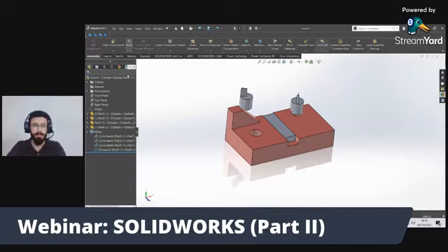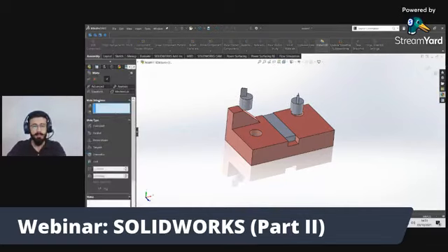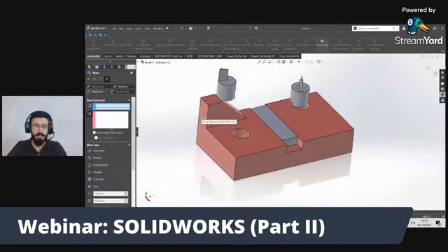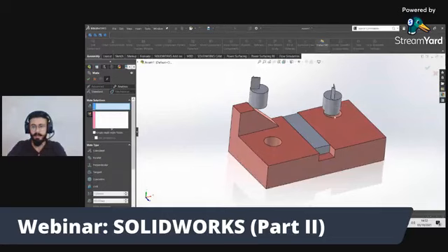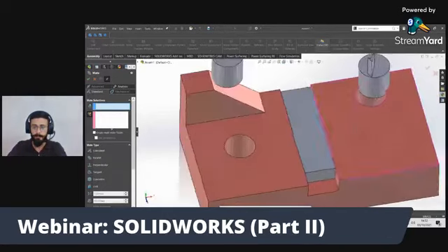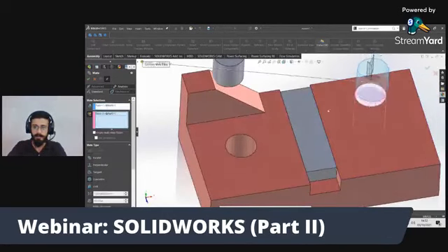Go to mates. There is a multi mate. Select this face, this face, this face.